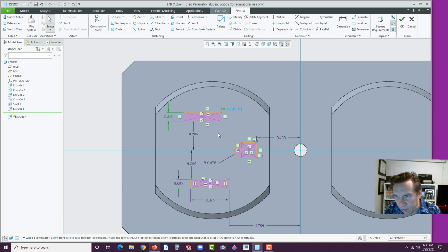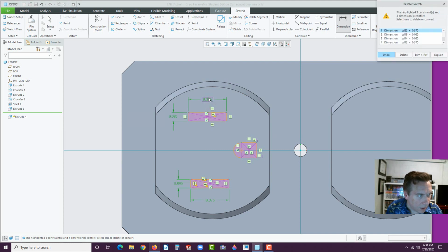It's 0.725 from center here. So from here to here. Whoops, make sure dimension tool is on. From here to here. 0.725. Okay, and last one is this length here. Needs to be 0.3. It got tied into equal distance there apparently.